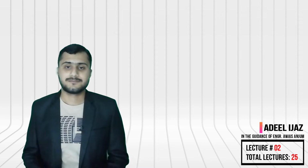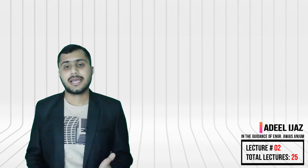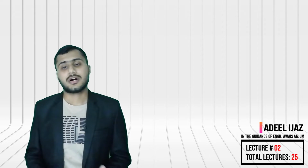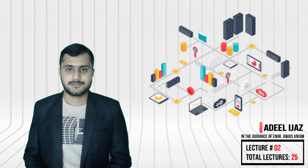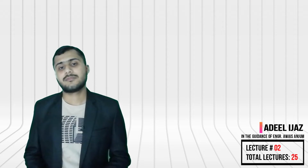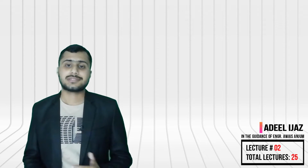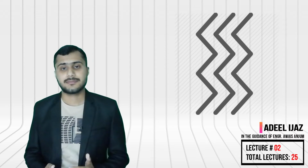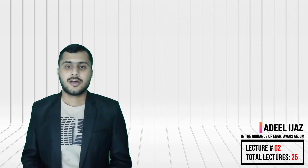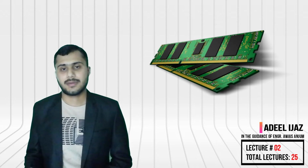to run our systems. PLCs can range from small devices with some inputs and outputs, also known as IOs, to large rack-mounted modular devices with a count of thousands of IOs, and which often network to other PLCs and SCADA systems. They can be designed for multi-purpose digital and analog inputs and outputs. They are also designed to withstand extended temperature ranges, electrical noise, mechanical vibrations, and impact. Program to machine operations are typically stored in battery backed up or non-volatile memory.